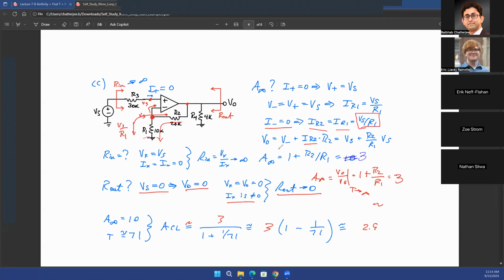So if you know that, your VO, that is the voltage at the output terminal, is going to be V minus, the voltage at the op-amp's negative terminal, plus the voltage drop across R2. What is the voltage drop across R2? IR2 times R2. The current through the R2 resistance multiplied with the value of the resistance, that is the voltage drop across R2. So the voltage at the output of the op-amp is going to be the voltage at the negative terminal of the op-amp plus whatever voltage drop you have across the R2 resistance.